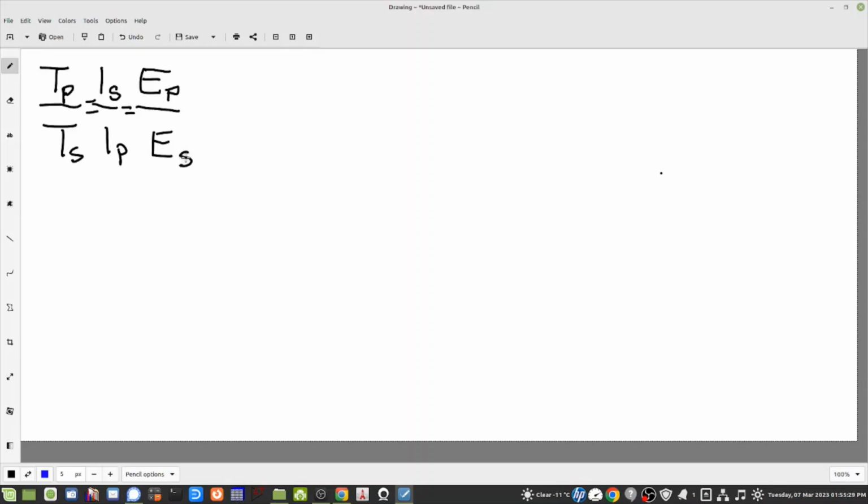Now look at this. I've remembered this since 1973 when I learned it. It's so easy to remember because it's a tie formula, like you wear a tie. You start with the first letter of the tie formula, that's your primary. Primary, secondary, primary, secondary, primary, secondary. That's all there is. So if you know the voltage of the secondary, you input it, and you read it on the primary voltage, take that equation, that fraction, and that will give you the turns ratio, N.